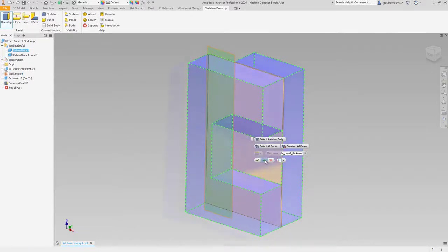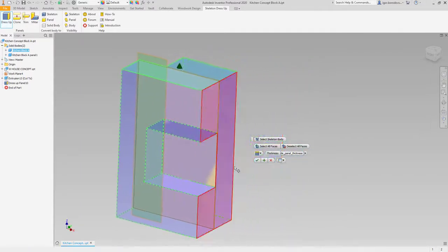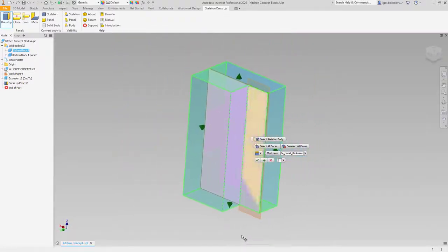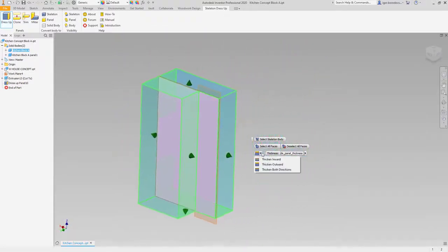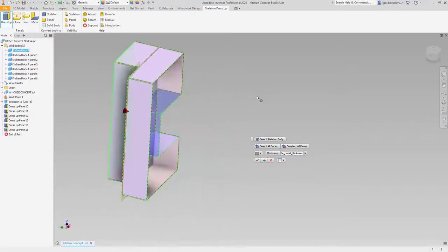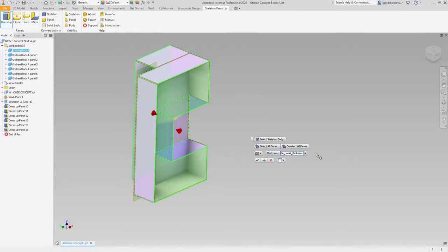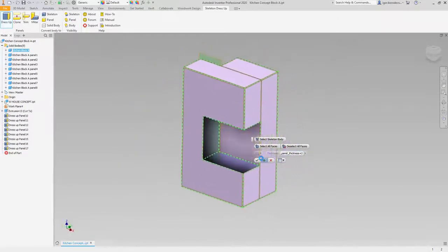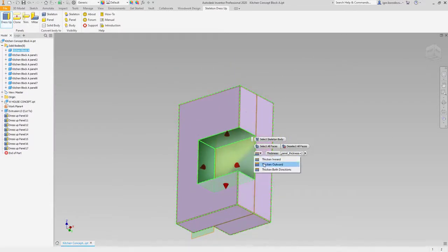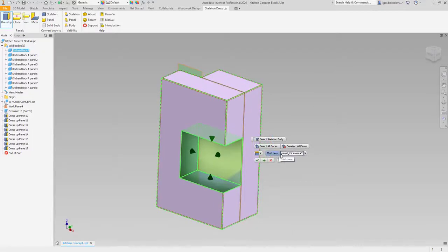That's it. Outer panels can be generated in a similar way, but in this case, we need to pick the face of the box. The front and back panels will be converted to door leaves. Therefore, I'll make them thicker by 2 mm, and later this excessive thickness will be reverted to the right value. The niche will be made of thicker, solid wood panels, so we must change the direction and the thickness parameters as well.